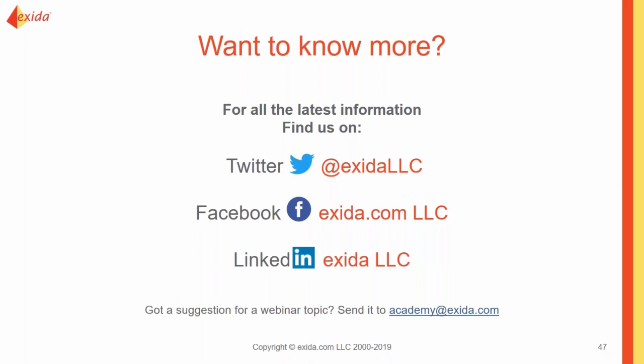So the first question we have is about architecture. There was a comment saying a lot of exida certificates seem to be Route 2H. Why? Yes, you are absolutely right. Well, in 2010, when Route 2H was introduced, it was introduced because people were trying to cheat the system with safe failure fraction and entering a lot of no effect failures into the calculation.